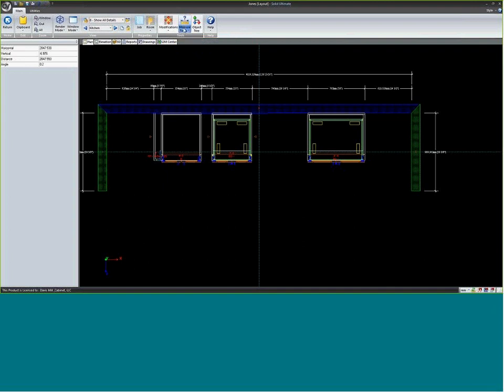If I go to the bottom half of this tool, I change to snap marks instead of measure. So I'm going to change to snap marks. Notice it changed this icon. So now if I click at different places, and see the little red crosshair, if I click in different places, those red crosshairs will stay in place. I can push my tab button, and notice in the upper left-hand corner, I can key into the horizontal.